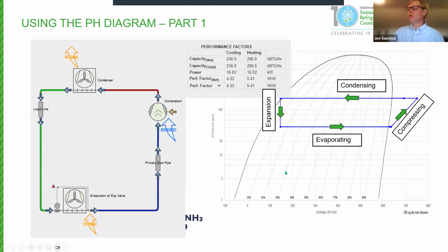The other thing about this is we don't have a time aspect. So there is no way of knowing what mass flow is happening. And we also don't know what the heat exchanger efficiency is either, right? We just know what the inlet points and the outlet points are, but we'll need mass flow to do that. So let's take a look a little closer at heat exchanger capacities and what influences them.